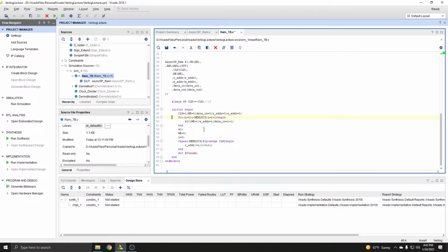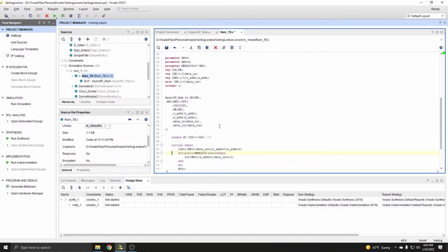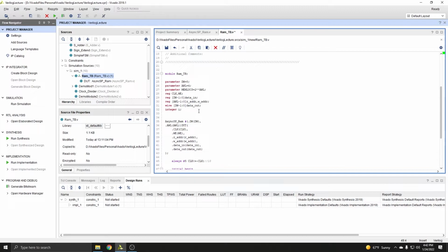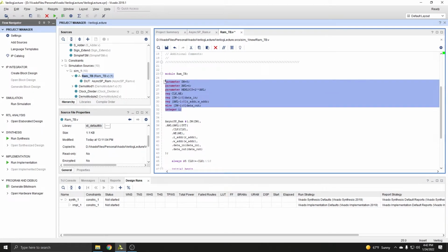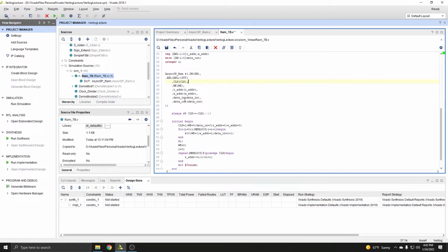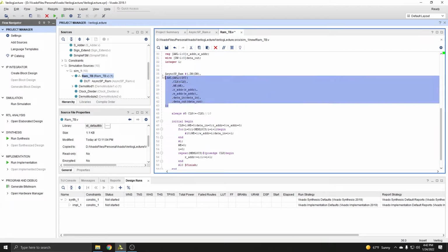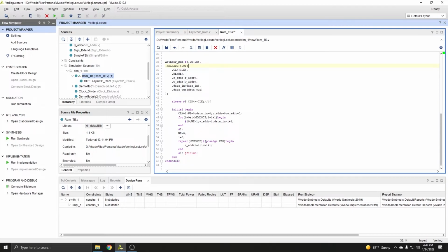This is basically the format for every test bench you should be demonstrating to me in this class, and basically any time you write Verilog: you have all of your declarations of variables or parameters or integers, the module that you're testing, then, if you're using a clock, your clock generation, and then your initial begin end, which is your actual test code.